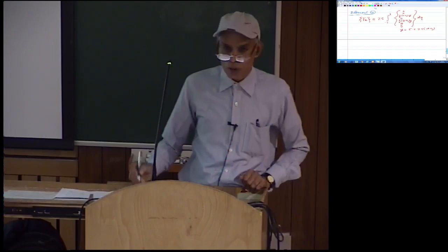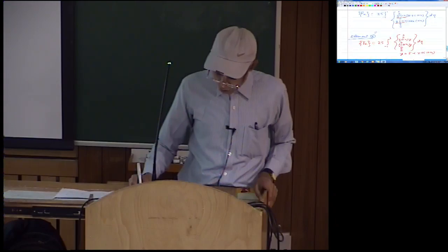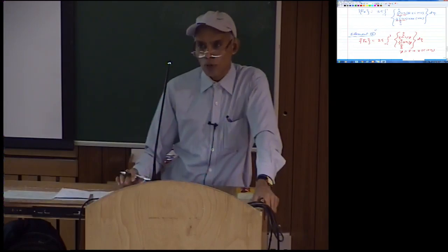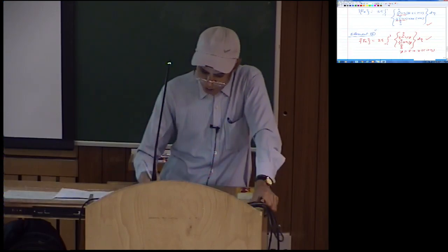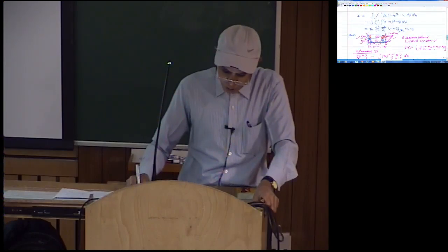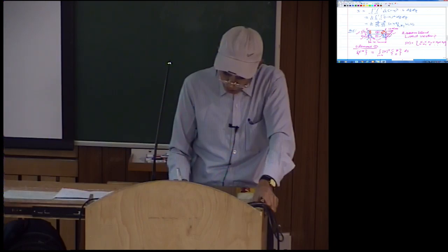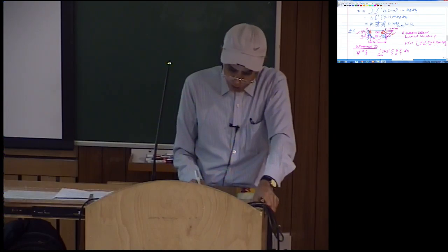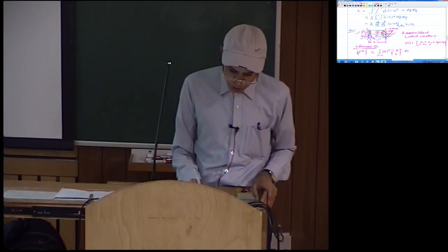Now finally the assembled load vector. So the assembled load vector is going to have contributions. So this is what you need to do, first step, that is due to the given known load, what are the contributions to the load vector, first element, second element. Once you have done this, this is actually straightforward. And then the assembly: when you look at the assembly, it has to have contributions due to the external force you are calculating because of this distributed force from here to here as well as here to here. In addition, at global nodes 3 and 5, you will have reaction forces. Those are from the distributed reactions on this edge.